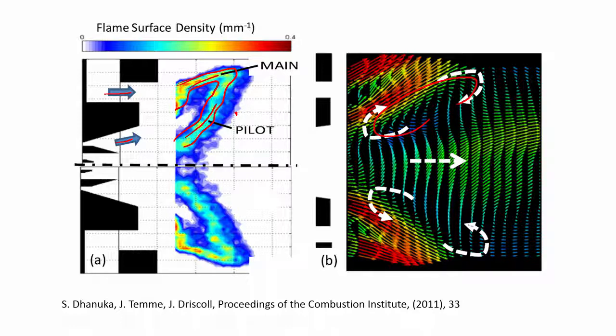Okay. And you can see this recirculation zone structure that is created due to the presence of the swirlers, and that essentially helps in stabilizing the flame, whereas at the center you do not have a recirculation zone, because from the center you are injecting this straight pilot fuel air mixture, fuel and air separately, and then that creates a pilot flame. Okay. So, this is how a modern combustor works, what we have discussed essentially. So, that is the idea.